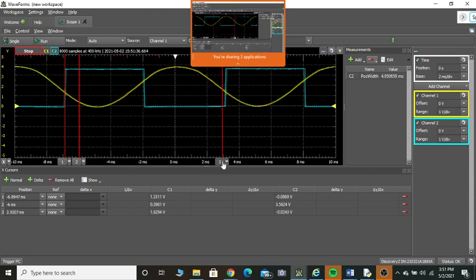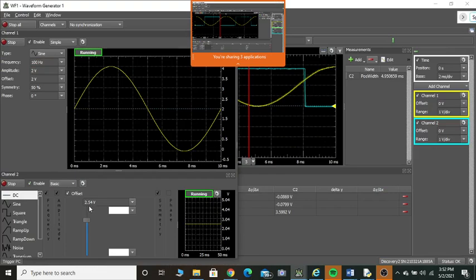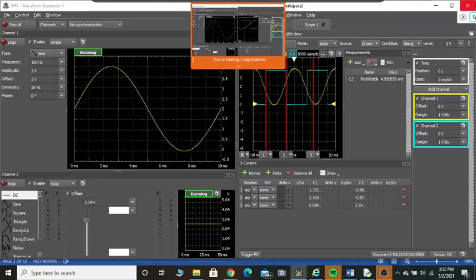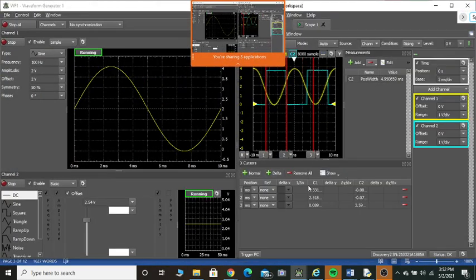let me take out. How do I take out this? Okay, let it be here. Let me just take this and put it here. Can you see VTH is almost equal to control voltage, which was 2.5. Okay, let me just place this here. Is it almost 2.5 volts? Can you see this is also 2.5? This is 1.3. Half of that, close to that. Correct.